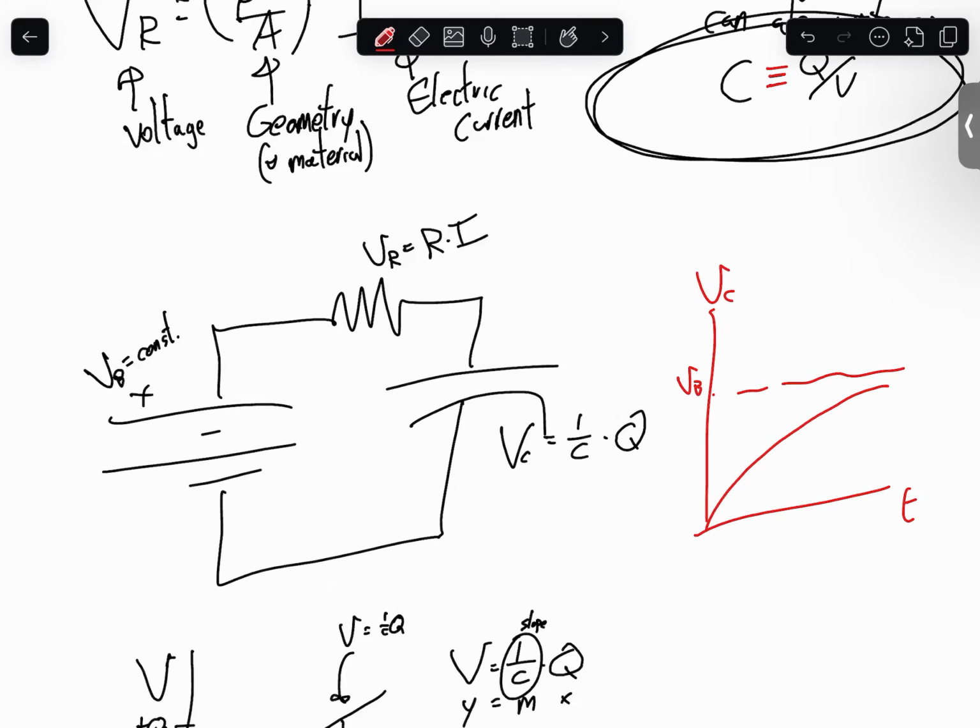David: Is the voltage negative 9 volts on the other side of the capacitor? We usually define the negative terminal of the battery to be 0 volts. Correct. That's the reference. Theoretically, once this is fully charged, you could say this point is 9 volts less than this point. If you define this to be 0 volts, then this would be negative 9.